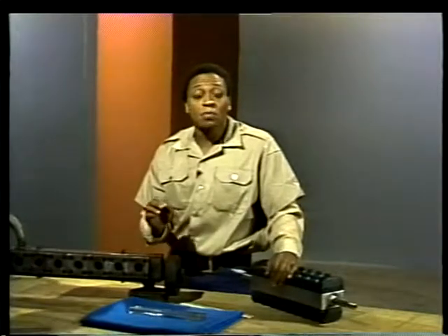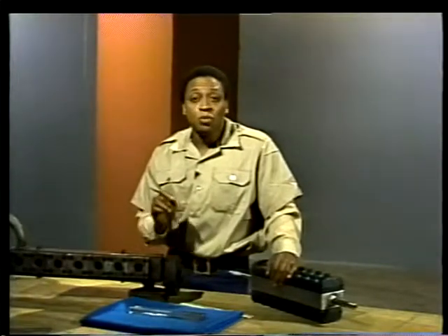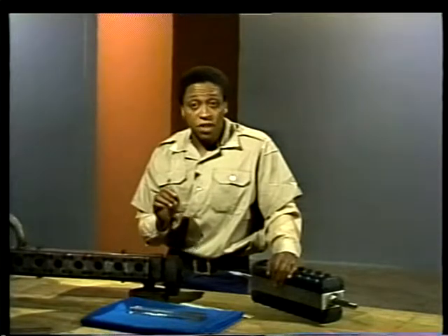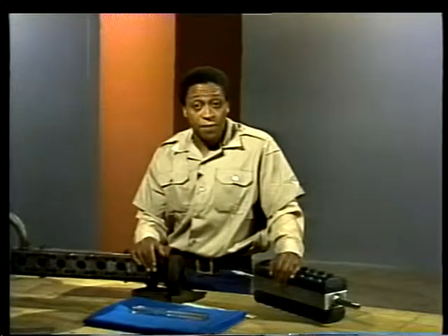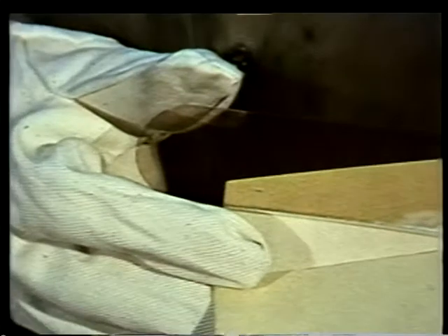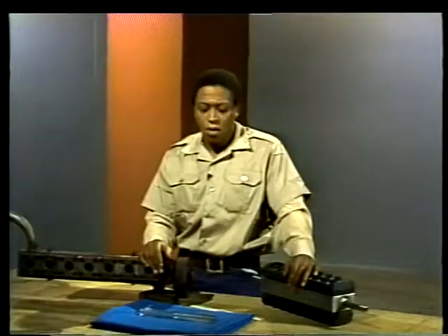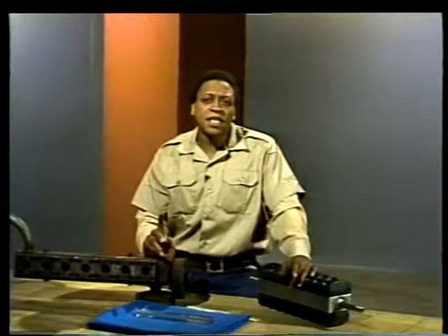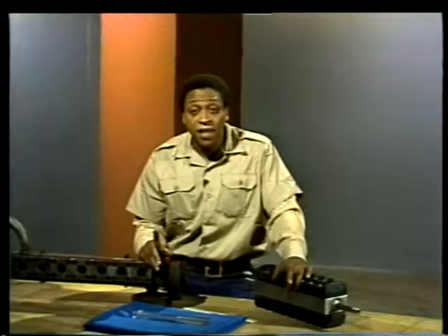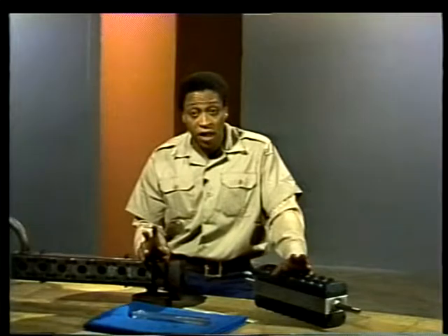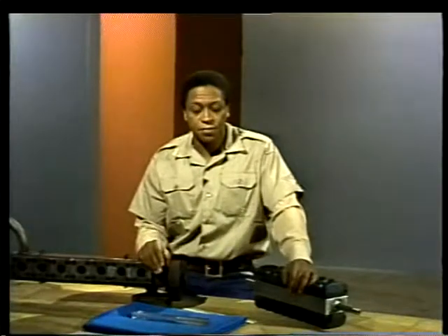The same rule applies to the mica. New mica must always be used, even if the old mica looks okay. Whenever you handle new glass and mica, wear gloves or use lint-free rags. Once the gauge has been cleaned and inspected and new glass, mica, and gaskets are available, the gauge can be reassembled.